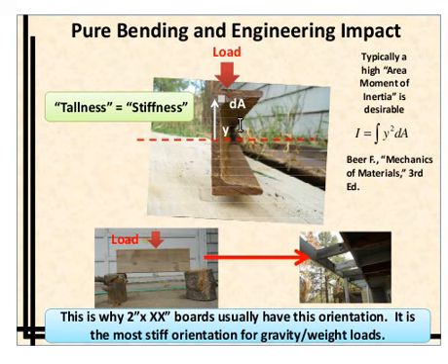And this is also part of the reason you'll see your 2x4s oriented in this direction as opposed to flat, like when you're looking under the joists of your house or underneath your porch. In some sense, you can kind of think of this area moment of inertia, the taller your beam is in the direction of the applied load, the stiffer it's going to be.